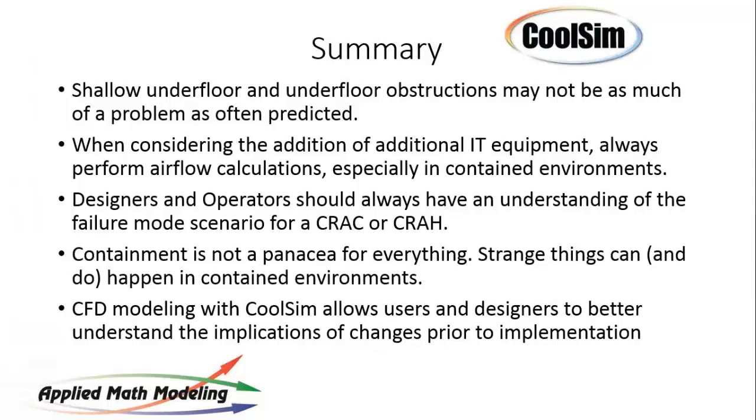So I'd like people to understand it's not always a case of a shallow underfloor, therefore I can't do it, or I've got too many obstructions, therefore I can't continue to use underfloor air distribution. It's case specific, and understanding what your data center looks like and where the major blockage is is important to analyze.